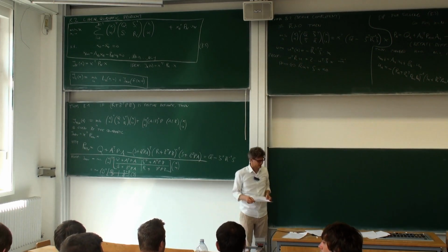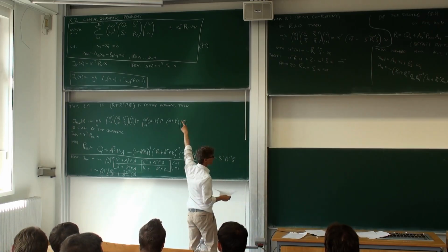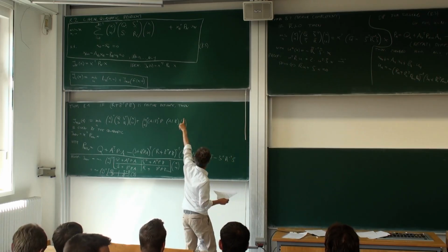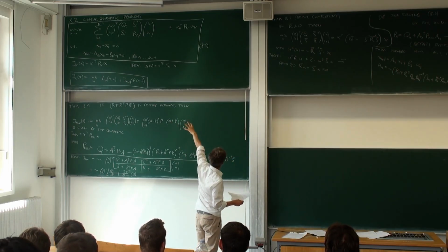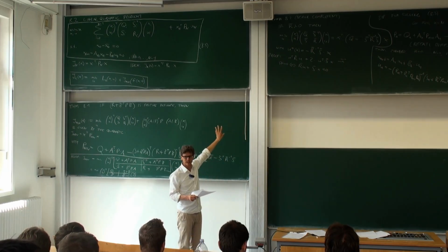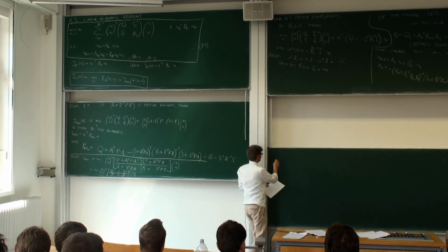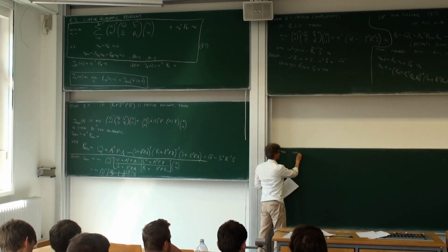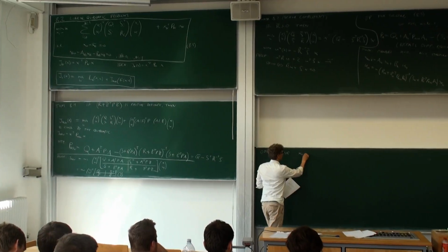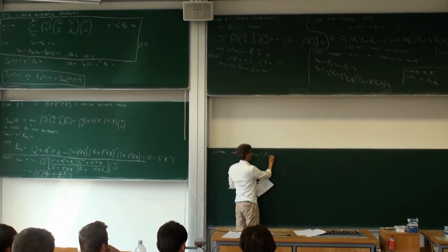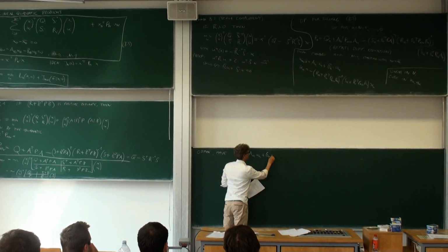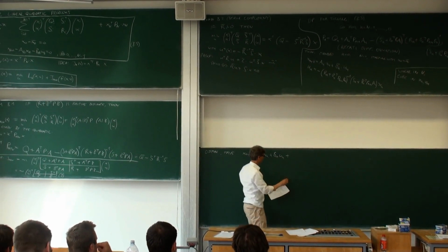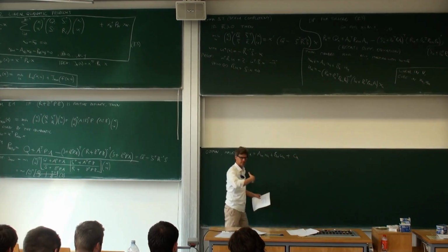And that is that this linear quadratic problem that we looked at is a bit restrictive. In many applications, we will not actually have a linear system, but we will have an affine system. So very often, we will have something more general. We will have a system given, for example, by x_{k+1} = A_k x_k + B_k u_k, but then plus a vector that I could call c_k. So it has some affine term.